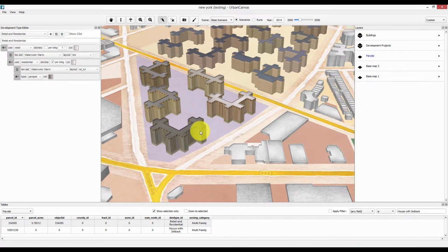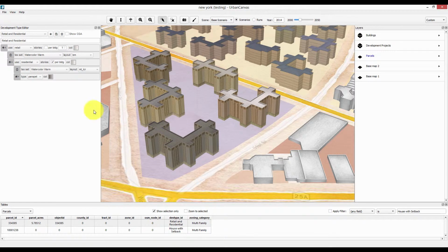Let's add a little bit more complexity. What if you want the residential units to be set back from the retail below? Select the roof surface of the retail block and split it into 5 resultant surfaces. Assign a 1 meter offset value to split the surface.